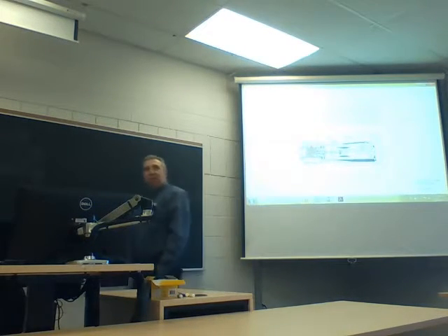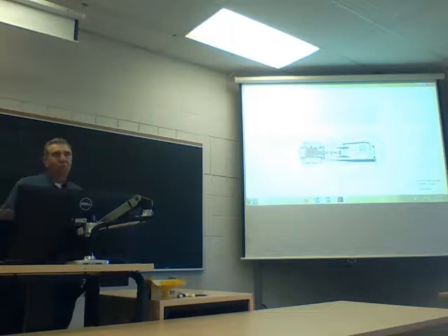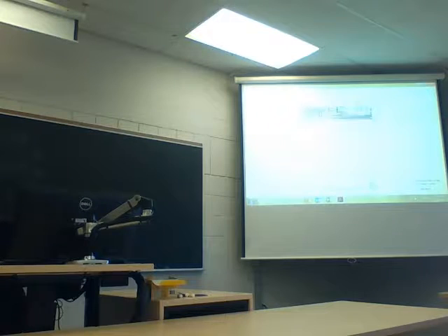You got oil in it, right? So the problem with a strict reciprocating compressor is actually delivering oil-free air, because sometimes the rings and the cylinders are going to leak. Sometimes you're going to have a carryover of the oil because you've got oil on it. A lot of the other compressors, we don't use that kind of oil, so we can get away with less oil in the air, because then we've got to separate it.